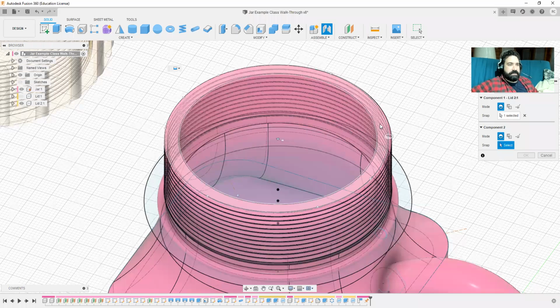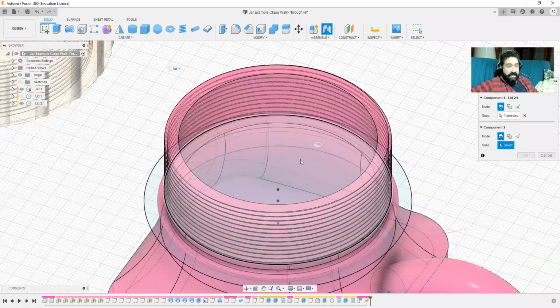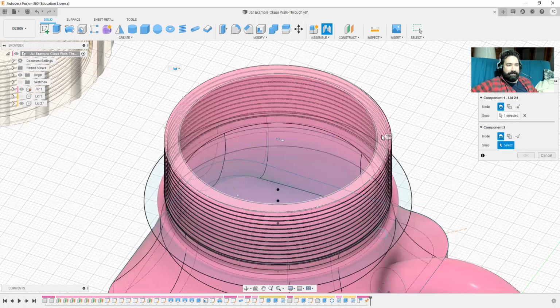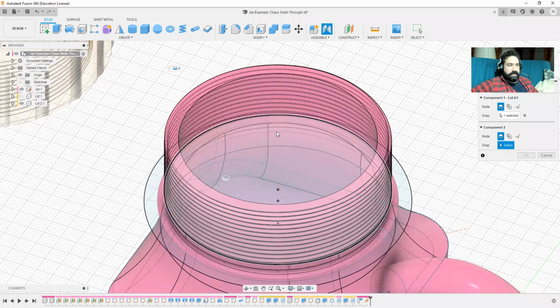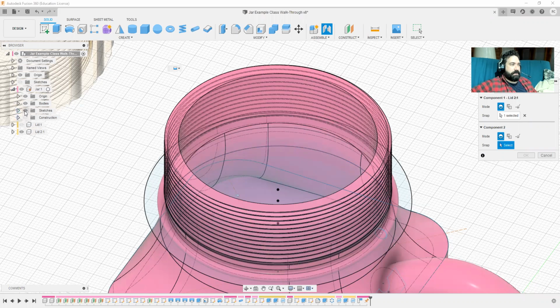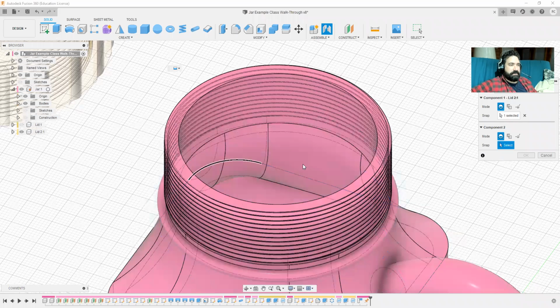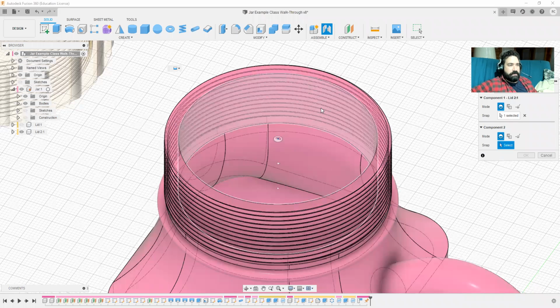I want the center of this cylinder, of this negative space, but the top of this lip. Again, there's literally nothing there for me to select. If I mouse out there, it tries to select one of the sketches down below, which doesn't help. So one of the things you can do is go over and hide the sketches. That helped somewhat, and you can see if I'm really careful, there we go.